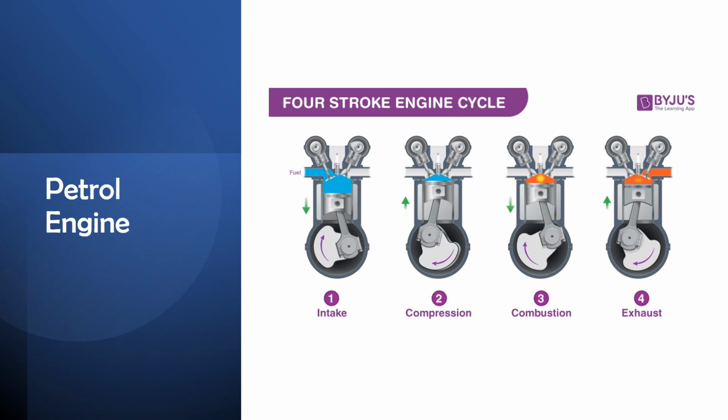The piston moves back upwards and the air gets compressed up to a compression ratio of 10 or even 14 to 1. Now on to the important step. The air-fuel mixture, or in case of a direct injection, the fuel gets injected shortly before the piston reaches the upper dead point and ignites the compressed mixture shortly after. Because of the following so-called explosion, the piston moves back downwards, which is the time the piston generates torque.